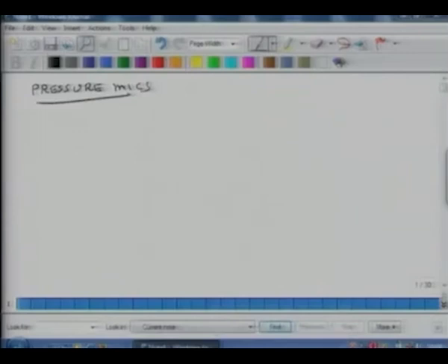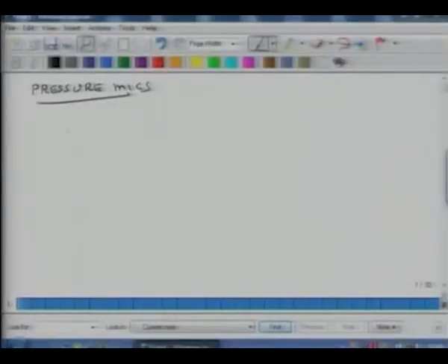Within pressure microphones, there are different types or categories of microphones. There could be electrodynamic microphones, condenser or capacitor microphones, piezoelectric microphones, carbon microphones. We will very briefly capture all of these, but let's start understanding how a pressure microphone works. Essentially, a pressure microphone has a casing, and then I have a diaphragm which is attached to a suspension system. This is my diaphragm. This wiggly line represents the suspension system, so the diaphragm can move in and out.